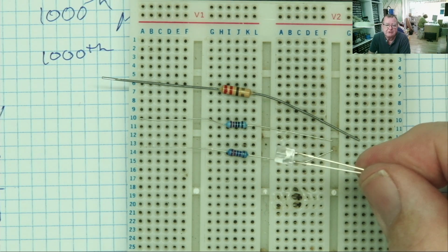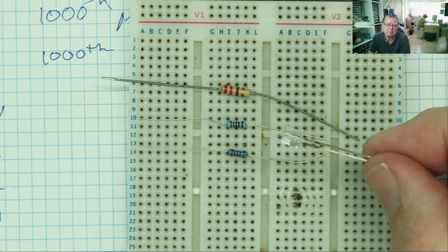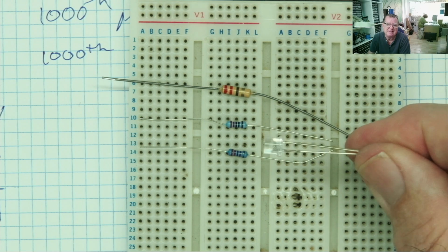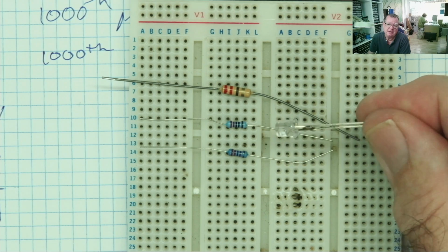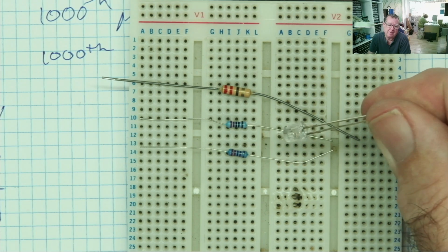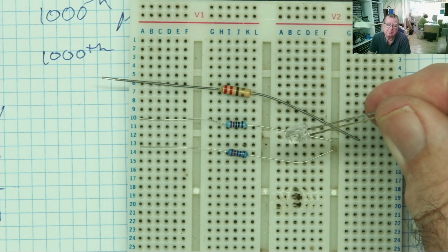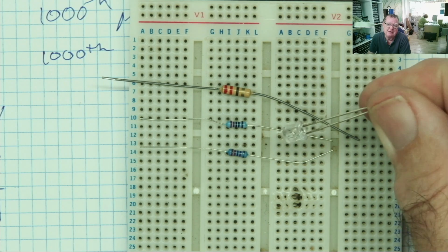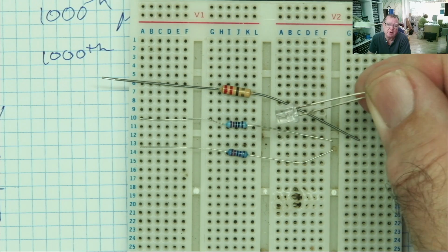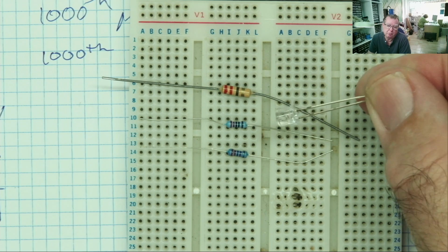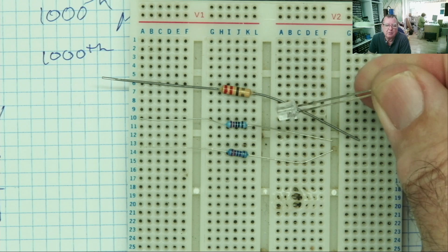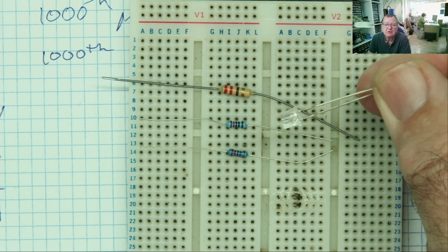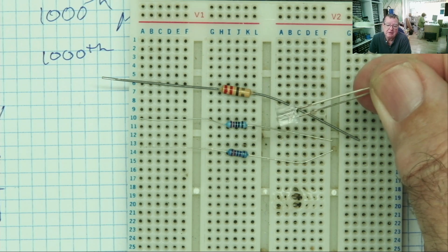Also, to complete our circuits, we need some sort of indicator. This is an LED, light emitting diode. We haven't talked about these yet. You may well have heard of them. Imagine this like a light bulb, basically, but it also needs a resistor in series with it to limit the current that flows through it. Otherwise, the bulb will blow. So don't worry about it too much. It's just an indicator so we can see what's happening in our circuit. We'll cover these in detail a little bit later, of course.